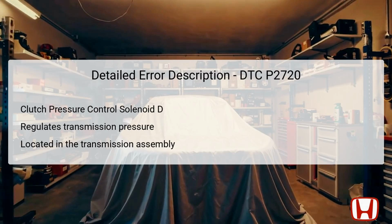The AT clutch pressure control solenoid valve D is responsible for managing the hydraulic pressure applied to the transmission, which ensures seamless gear shifting. This valve is integrated into the valve body assembly of the transmission, making it crucial for optimal performance. When the solenoid receives electrical signals from the PCM, it adapts the pressure based on real-time driving conditions. Signs of failure can lead to erratic shifting or total inability to shift into certain gears.